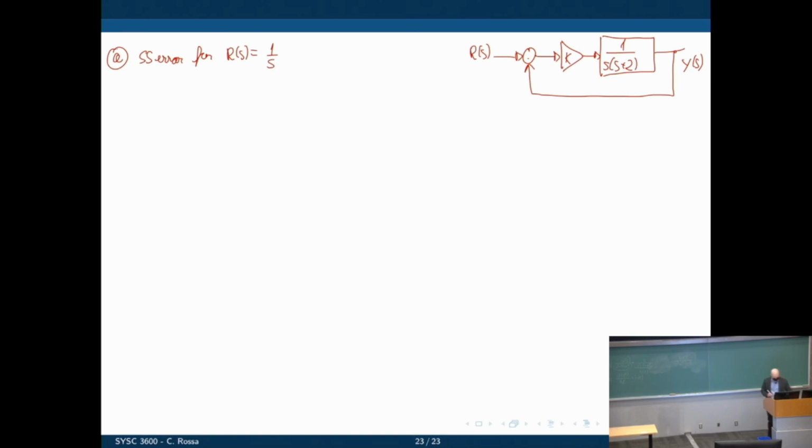So what is the step input in this case? In this case, we tell the robot to go to, say, 10 millimeters. You see the equation, the desired motion goes from 0 to 10 and it remains at 10. So that's a step input. So this is 1 millimeter. So to find the steady state error, we will need to define the error first, which is right there. That's the error as a function of time. And we are going to define the error then as the desired position R of S minus the actual position Y of S.